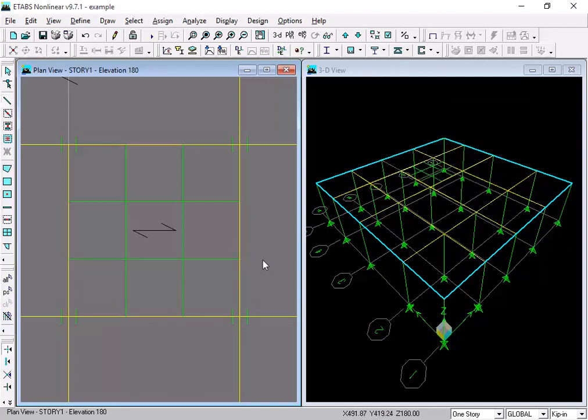Okay, so you see that I have marked the boundaries of my opening, right? This is the middle third of the slab from both sides. Now I can create an opening. It's very easy. Select the slab, and select all the 4 lines